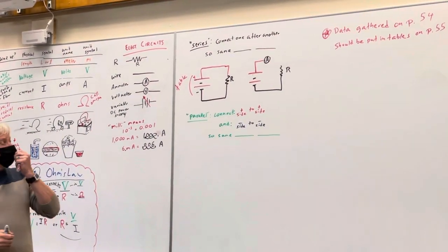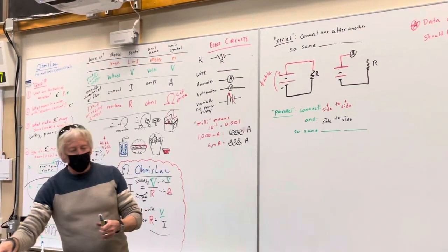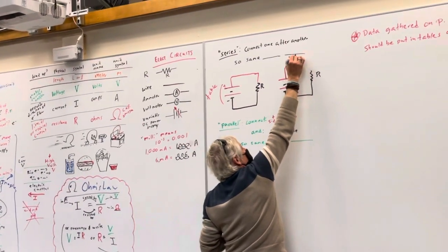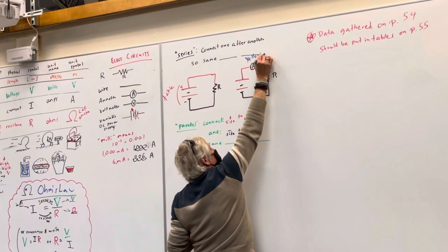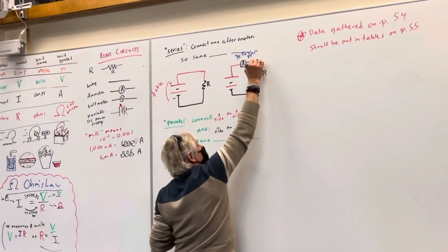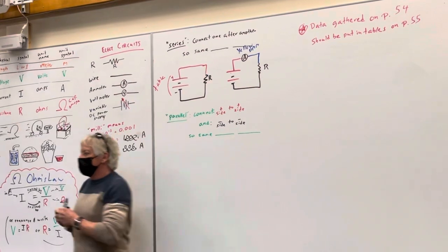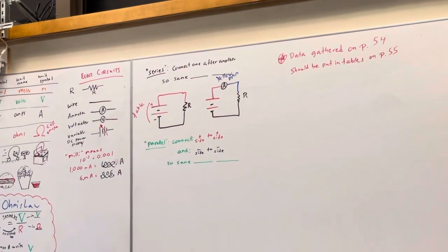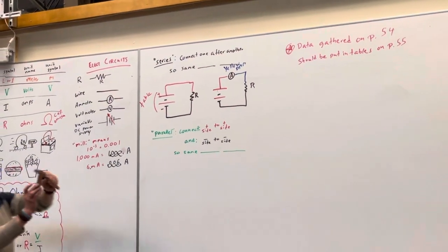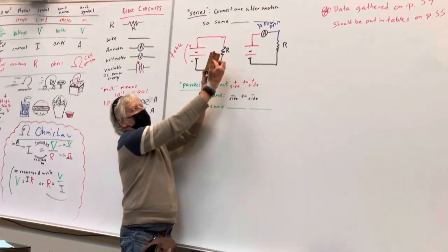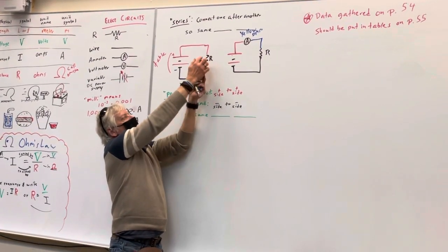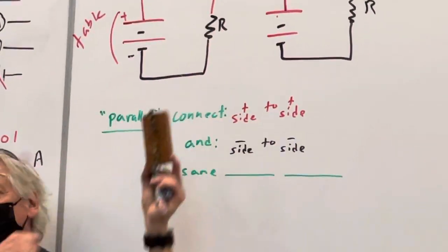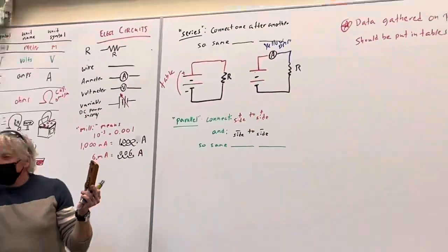And it doesn't really matter. You're actually going to use a black wire out of one side. So this is that yellow box, yellow DMM. And then you're going to use a black wire to go to one side of the resistor. It doesn't matter where you connect here, anywhere along that metal, it's just metal. You're going to clip on there, and then you're going to bring it back to the black input of the table.